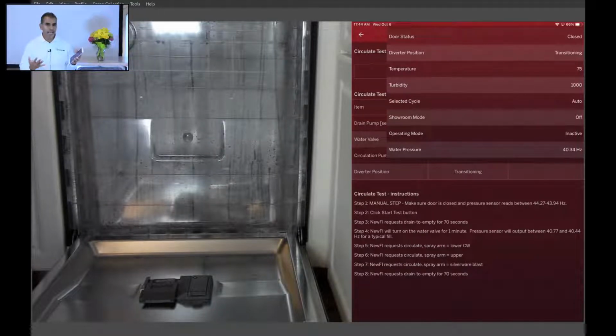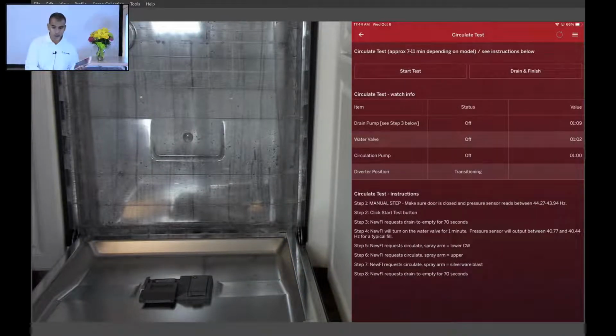So obviously I would have to activate the drain pump. That's what it's telling you. Now, fortunately, if you're a knucklehead like me and you forget to drain the water, what SmartHQ service is going to do, it is going to activate it for you. And you can see right here, the first step in the process is the drain pump will run. So we're going to go ahead and hit the start key, and we will hear in a second the drain pump running. There it is. There's a relay, and I can hear the water coming down the sink, whatever little bit of water was left behind. And of course, that's telling me that the drain pump is working.